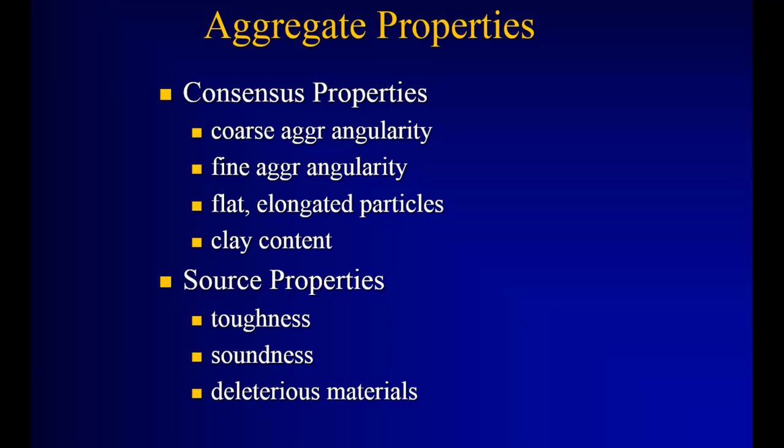and asphalt's an expensive component of these mixes. But on top of it, it's not very durable, and it inhibits coating, getting that asphalt film thickness when you mix it onto aggregate faces. So think of your coarse aggregate or your rock. When you're trying to mix that material together, if you got a lot of clay, clay is really fine, and microscopically, if you look at it, it almost looks like a saucer, a thin saucer.